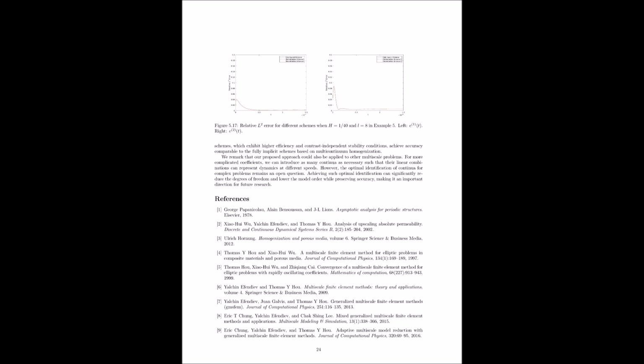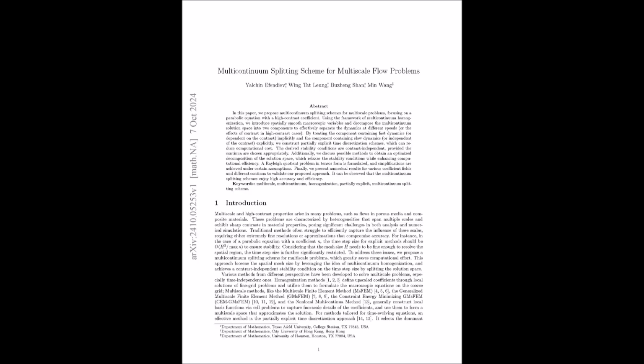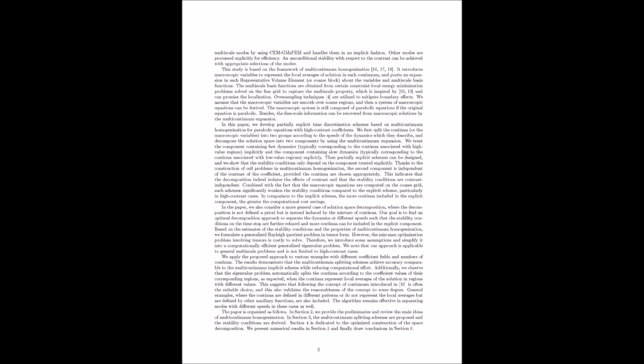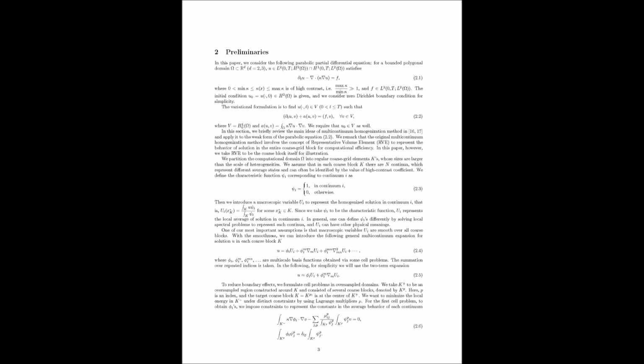Exactly. And to capture what's going on within each of these continua, we use what are called basis functions. So imagine each continuum as a puzzle piece. Solving these cell problems is like finding the right shape and pattern for each piece so that they all fit together to form the complete picture of our flow problem. Is it like that, the puzzle piece analogy? And the beauty of this is that it lets us use what we call a coarser mesh. Instead of those tiny little squares, we can use bigger ones, and that makes the computations way faster.